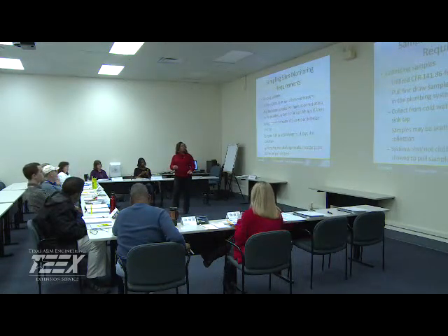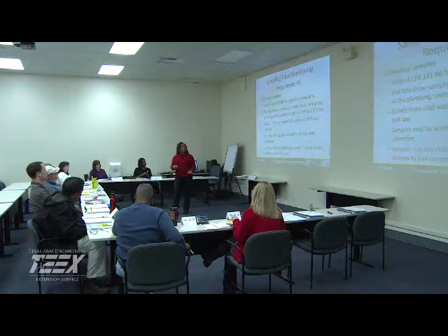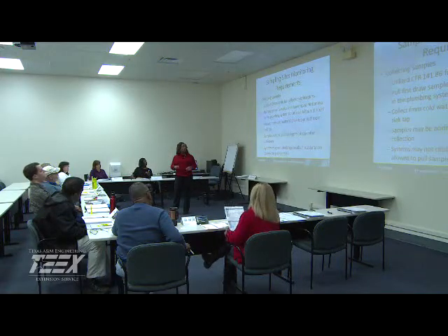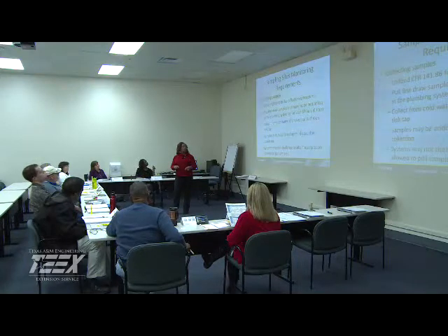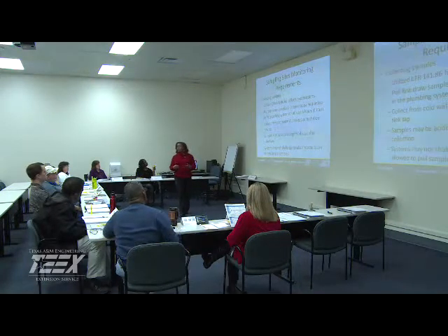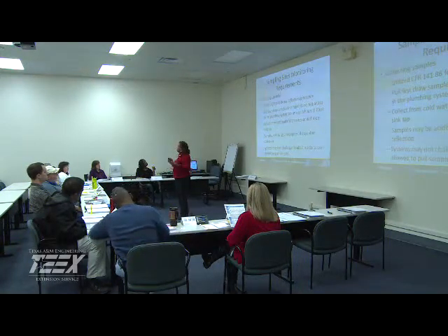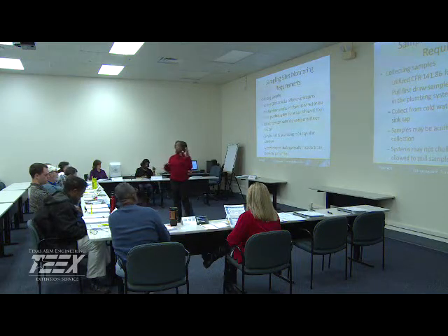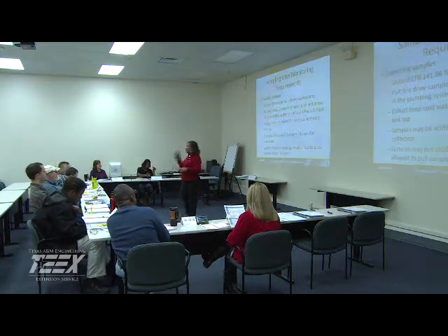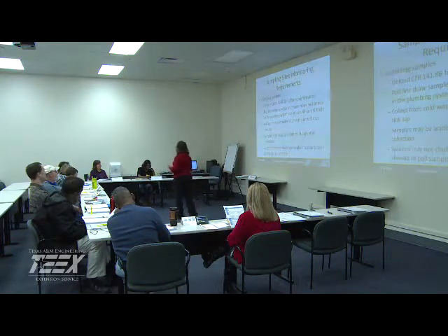We want to make sure we are following the approved procedures. Tell the residents, or make sure you have someone, pull the first draw sample. In other words, we want the water to stay motionless for at least 6 hours but not more than 18 hours, because we want to see if any of the copper and lead is actually reaching into the drinking water. So we want the first draw.